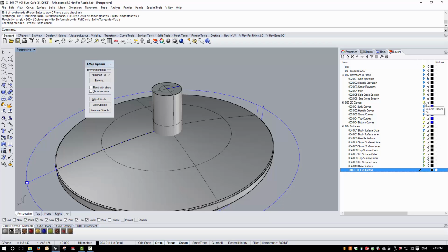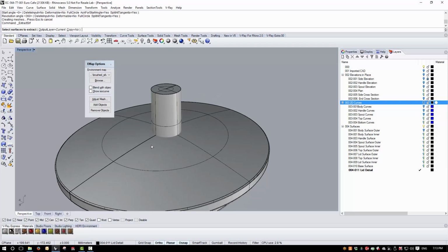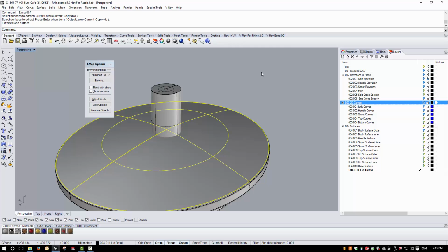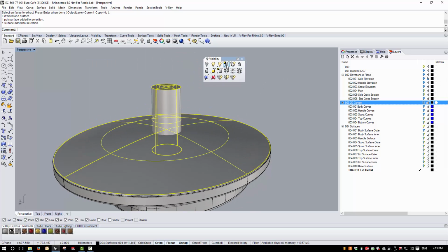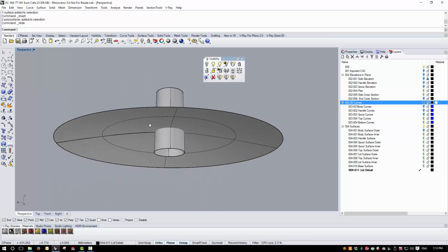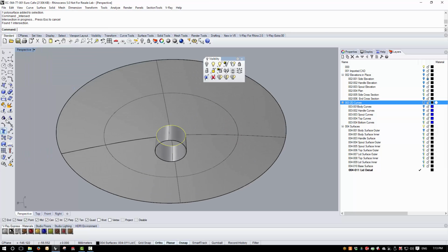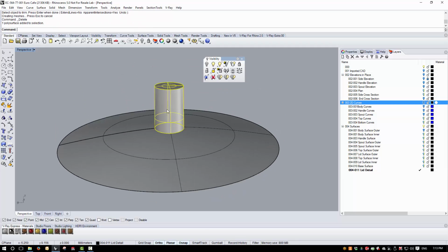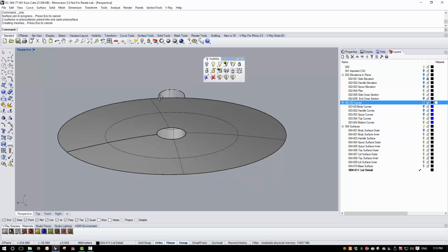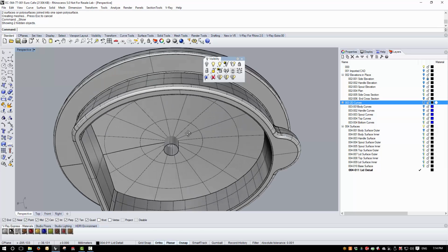Turn off my curves and just temporarily extract the top surface, and just with my visibility tools I'm just going to invert selection and hide objects, create an intersection curve here, trim these away with each other, and join, and then show the remaining objects,